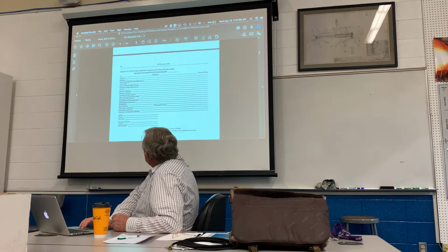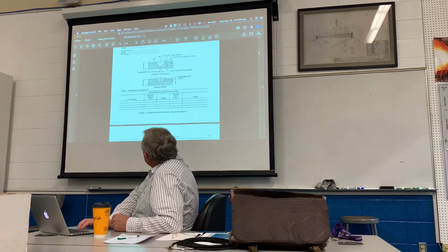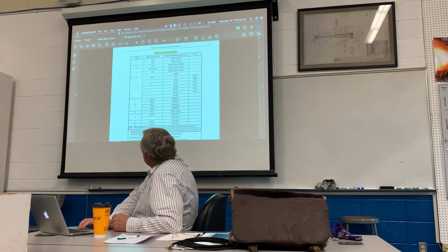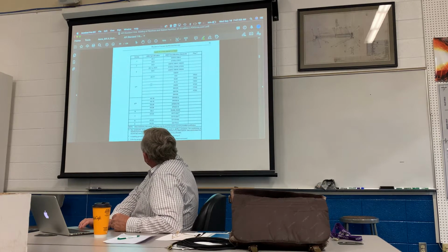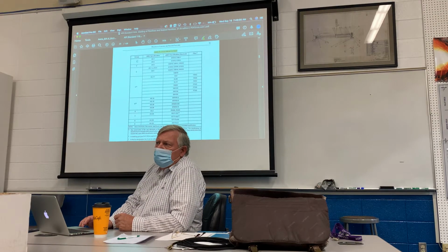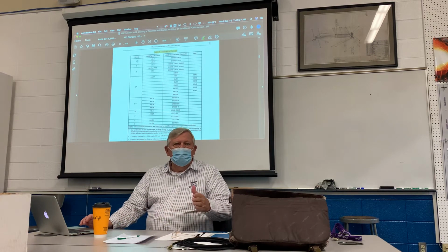So we've got the diameter and the wall thickness, we've got the joint design, filler metal and number of beads. That's what you're going to have to fill in there. For the root, you have to go down to the chart, which I believe is 2-1, right here, table 1. The grouping, if you recall from the code, can you use a group 2 electrode if you've listed a group 1 electrode in the procedure? No, because the code does not allow you to go from group to group.